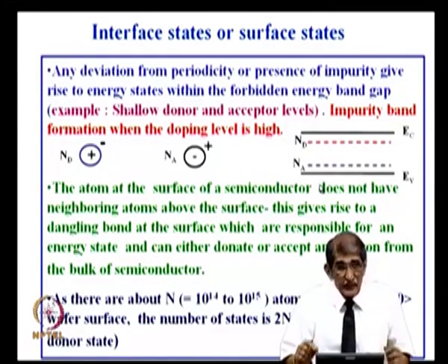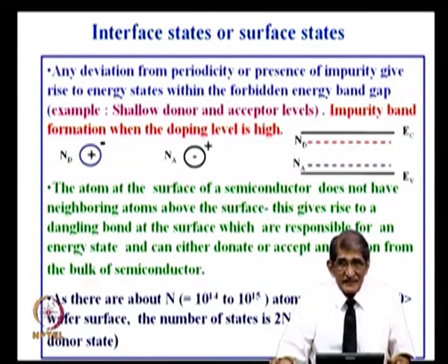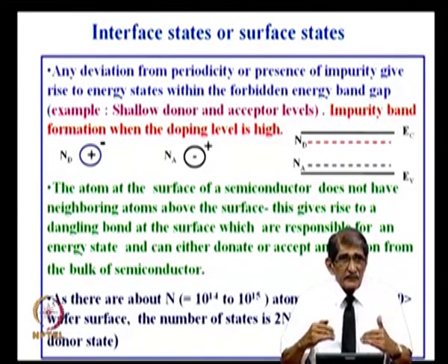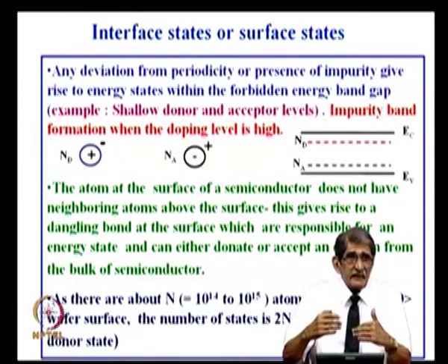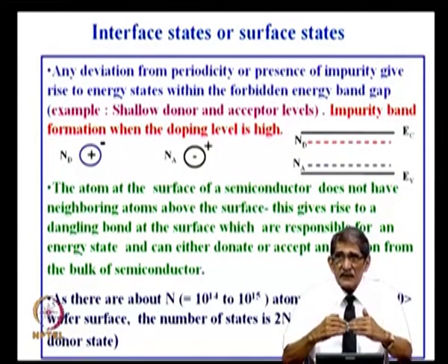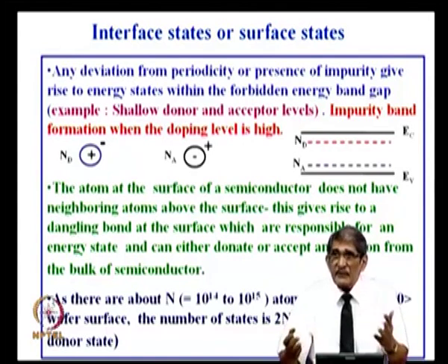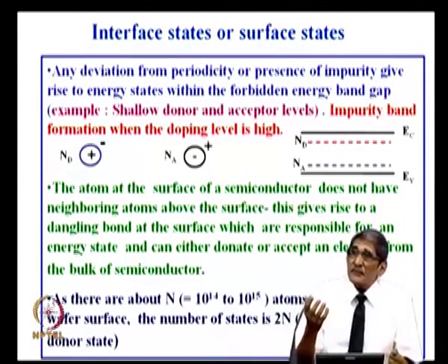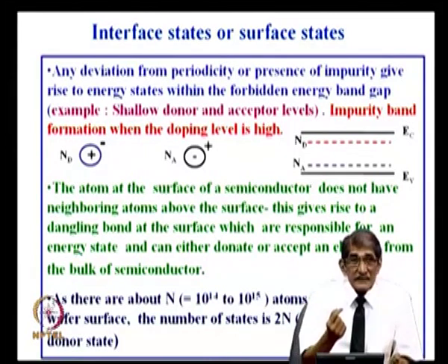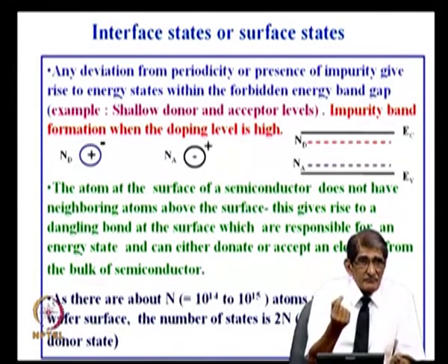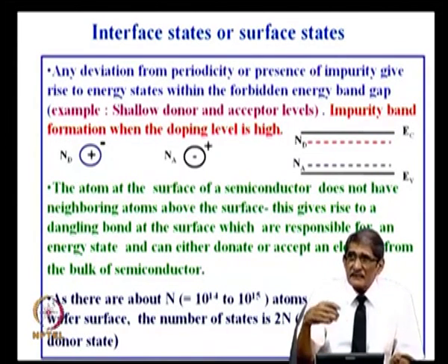So, now going back to the theory of surface states, you would have seen already. I have argued that if it is one atom, there will be one acceptor level and one donor level. It can go either way, it is amphoteric. For example, if you put gold into silicon, it has a single valence electron. It can either donate or accept.